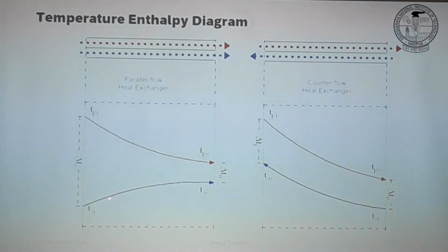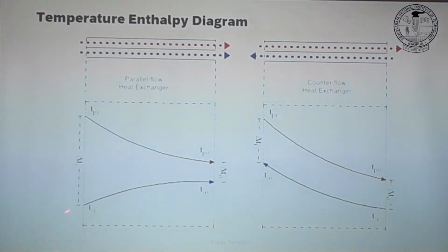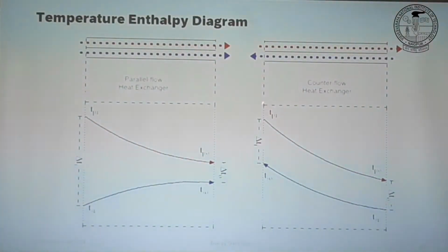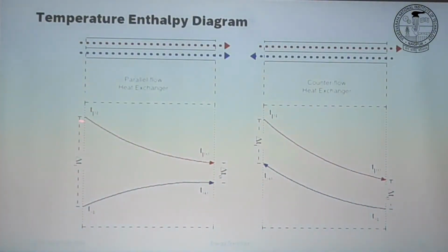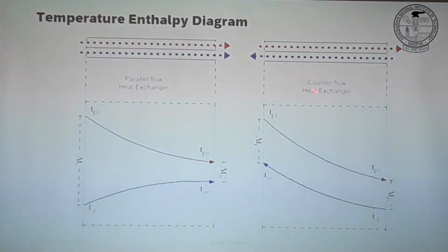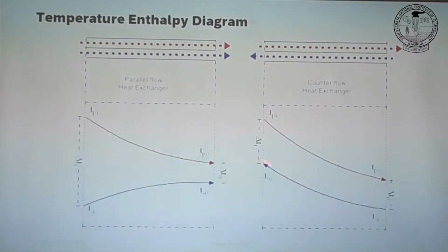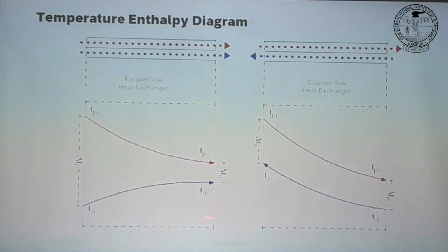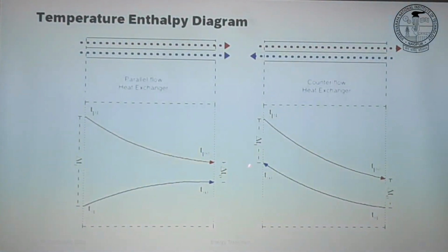That's inlet, that's outlet. Hot side, cold side. They are not crossing, right? Because curves start from like this and travel like this, and from the upper side it travels like this. So they are not supposed to cross each other, right? No, and they are not crossing. The same example with co-current, same example with counter current. So they are also not crossing anywhere. But you could see that's my starting point, right? It's my starting point, but I can have a very high cold outlet temperature.